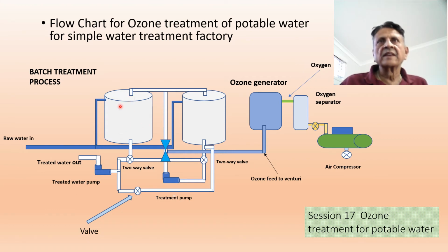Here is an improved version of that, where there are two tanks involved, so that while one tank gets treated, water is filled into the other tank, and by the time the water is topped up in this tank, the treatment will be completed in this tank, and ozone treated water will be taken through the two-way valves for consumption.